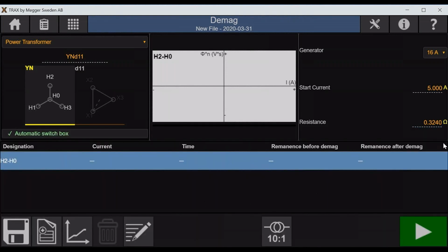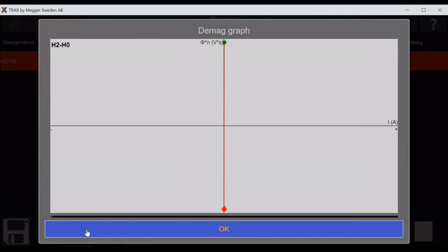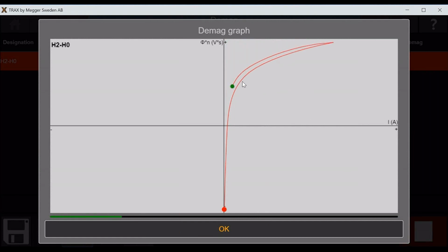the core. And if you already have the results from your winding resistance test, you can use the ohmic resistance information for this. With that being said, you just go now here, you have the information completed, and you will be applying the current right now, the DC field, into the central leg. That is by default. Now that we have a symmetrical distribution in the core, and you can see exactly what's happening. So we're looking for the maximum of saturation right now. We applied a positive signal. Now we're switching that to the opposite side.